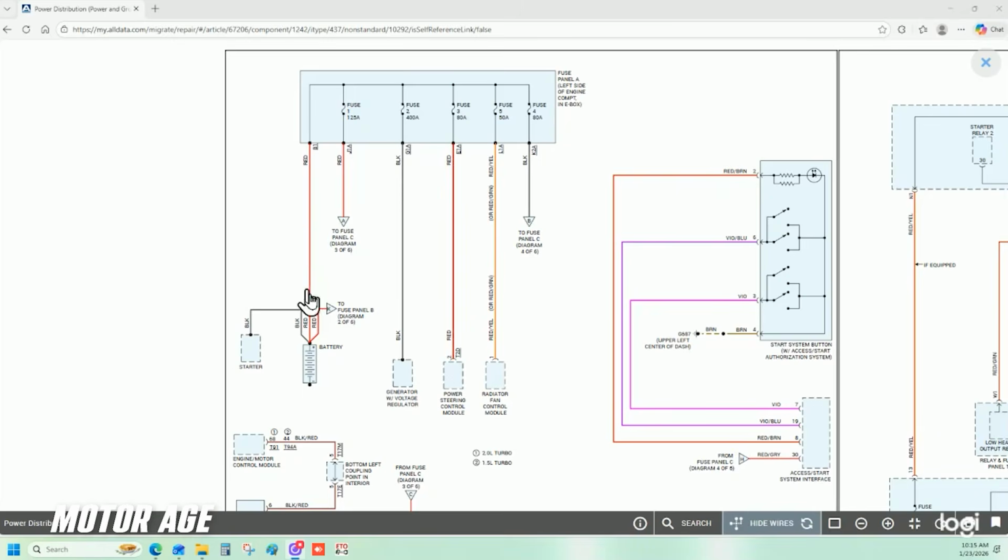So rather than approaching the vehicle as a whole and being totally overwhelmed or trying to troubleshoot this fault at random, we can strategize and capture the fault initially. Right here at this fuse panel A, located in the left side of the engine compartment behind the driver's headlamp, one of 5 pathways is the source of parasitic drain. So instead of attacking the whole vehicle, we will simply limit the fault to one of 5 pathways.